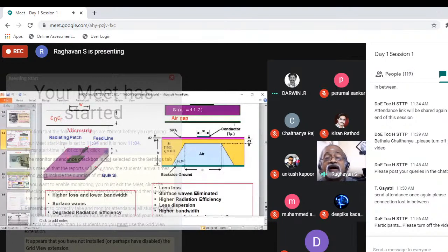And using silicon, you cannot remove it fully. You should remove only partially. If you remove partially, losses will be reduced. Every MEMS device you take, the cross section will be like this. So again, why I am telling this about MEMS here is that many of the MEMS cross sections will be a coplanar waveguide. So again, it is the continuation of the micro integrated circuit planar transmission line. Only the size will be different. Centimeter will become micro in MEMS. So this is again a very good